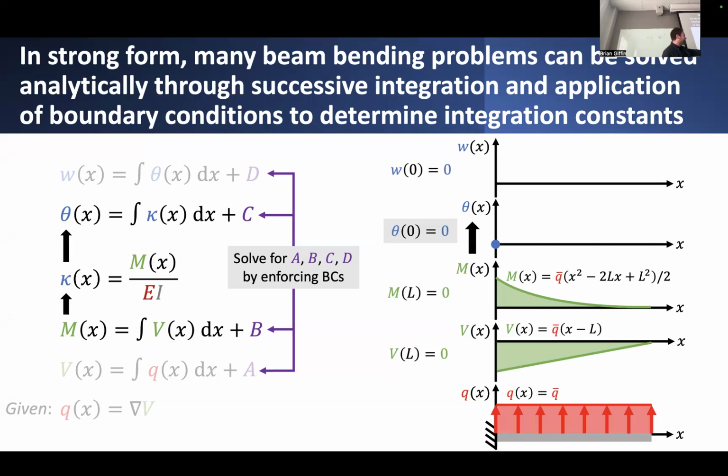But if I do everything with respect to, let's say, the principal axes of the section, such that I don't have that product of inertia term, or if I can reasonably assume that the section is symmetric, or doesn't include that product of inertia term, then I can just treat everything as an effective 2-dimensional problem. And then doing this inversion process is very straightforward. So a little bit of a nuance there, but relatively straightforward and not really a complication for most problems.